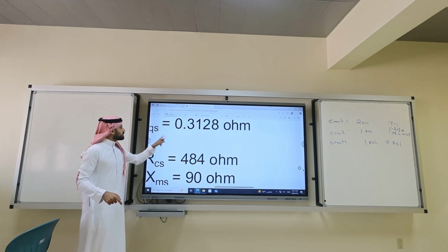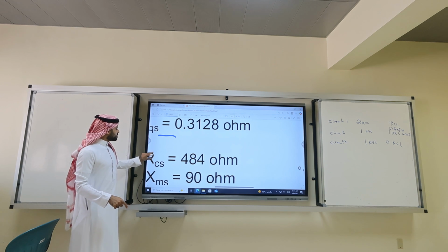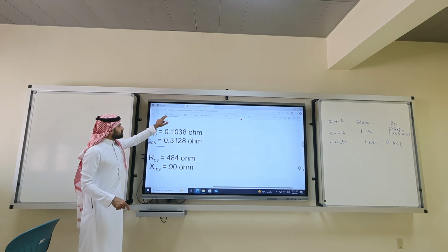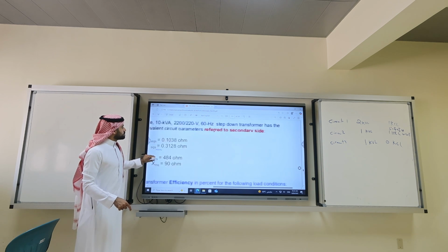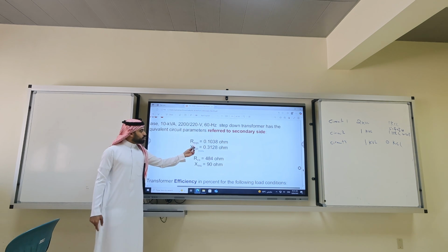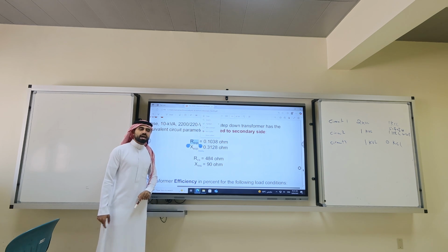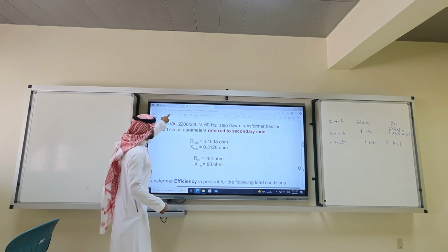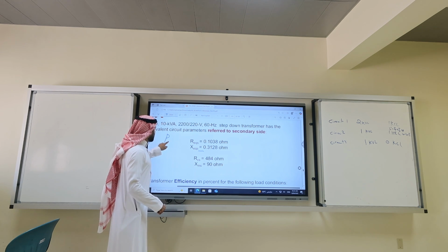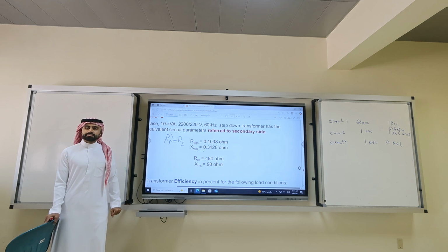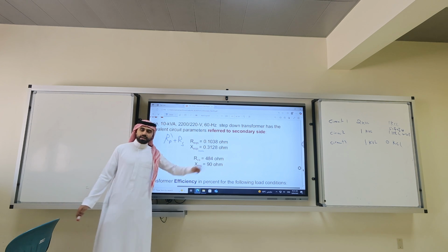What does the S mean? Secondary. EQ means equivalent. S here means refer to secondary. But what is this? This one is nothing but RP prime plus RS. Get it? This is second circuit. It's circuit 2 refer to secondary.